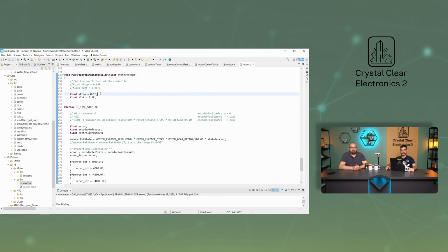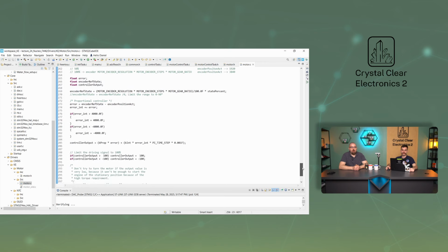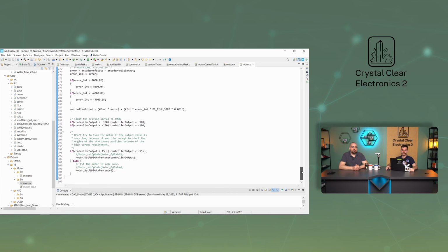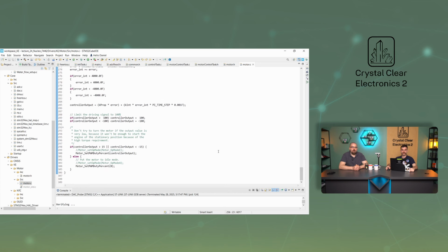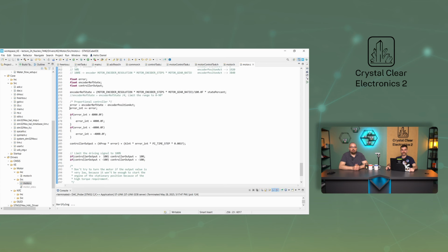Here, a PI-type controller is implemented to ensure that there is no residual error, so we can set the angle of the motor shaft exactly. The already familiar method of combining the error signal generation, intervention signal calculation, and intervention is also done here, and we also keep track of the sum of the error signals due to the I member of the controller. Once we have the valve control, our system is basically operational. Now we just need to add the extra features, such as saving data to an SD card.